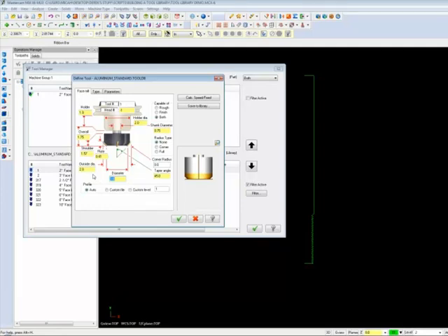The bottom diameter there is what Mastercam will use, so if you're cutting up against a vertical wall, Mastercam thinks it's got a tool diameter of 1.6, but if you've got a taper angle in there, your actual diameter is going to be bigger than that, and you are going to get a gouge. Now, that would show up in Verify, I would think, based on the tool definition. Would you agree, guys? Yeah, I believe you're right there, but you still have to be real cautious when using that. I agree.